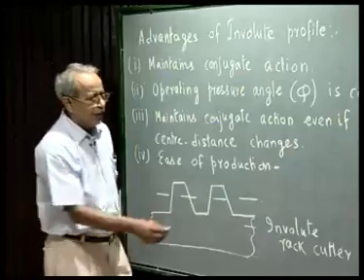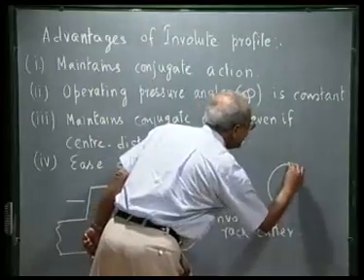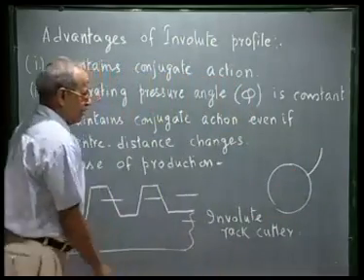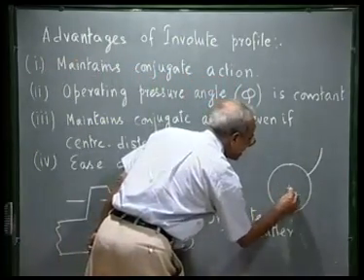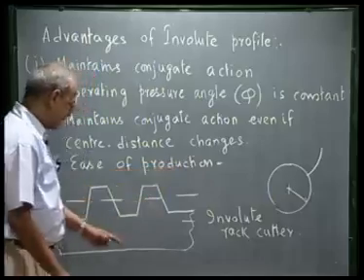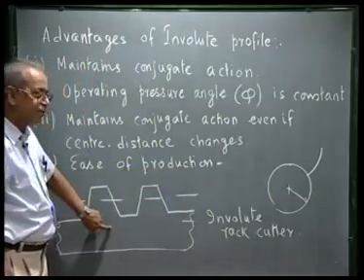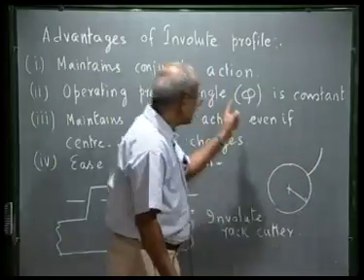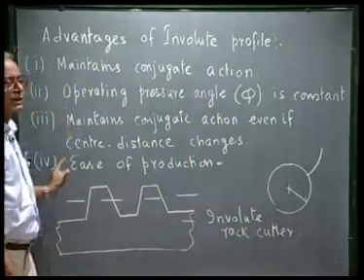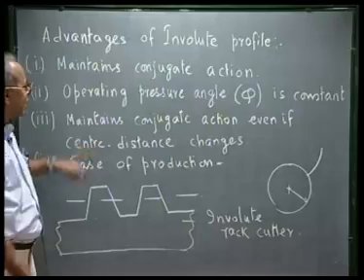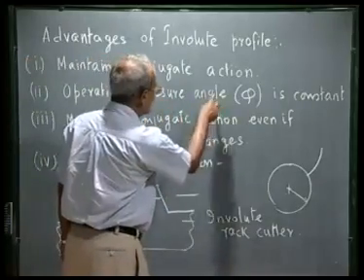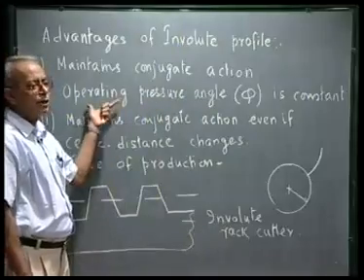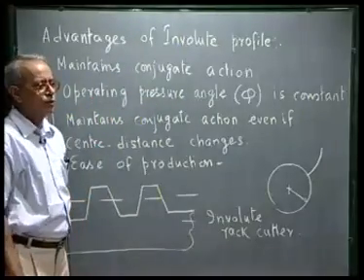Like we have seen, involute of a circle is a curve. So if the radius of the base circle goes to infinity when the gear gets converted into a rack, then this also becomes a straight line. All these points we will make clear in today's lecture. So let me get back to that figure where I showed the pressure angle, and now we will show what is the advantage of this pressure angle remaining constant in a pair of involute gear teeth profile.